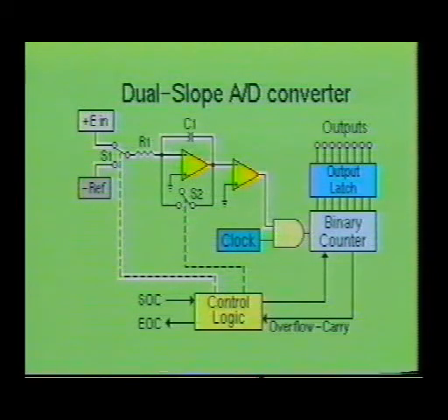When the positive analog input signal is applied, the output of the integrator section will ramp in a negative direction. This negative voltage will force the output of the comparator section high. The high output from the comparator section and the series of high clock pulses cause the main gate to produce a series of clock pulses into the counter circuit. This in turn causes the counter to increment. The counter is allowed to overflow and produce a carry signal, which is then applied to the control logic section.